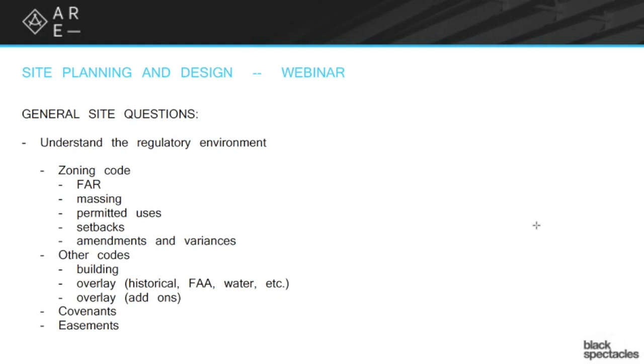If I'm putting up a wind turbine to generate electricity, I would definitely want to understand what the macroclimate wind directions are. So, like, is this a place where I have a consistent wind in a consistent direction? That's great. But if I put that then in an urban setting where there's a lot of turbulence because there's a lot of buildings, it's going to be meaningless. It's not going to work. I'm going to have to use a different kind of turbine that isn't monodirectional, right? So both of those issues, micro and macro, very important. You should definitely understand those things.